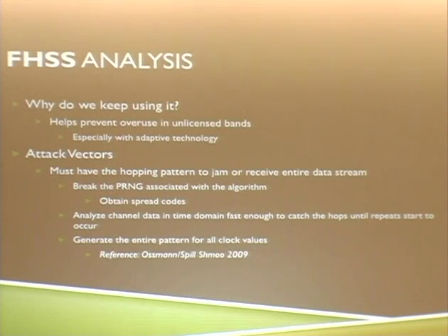So, frequency hopping analysis: why do we keep using it? It's very efficient, and what I mean is it keeps a lot of noise out of the bandwidth, right? There's an overuse problem, or people suggest there are overuse problems, in unlicensed bands, anything from 900 megahertz or any of the ISM bands. It's really good to use frequency hopping in those bands, and it is a good idea, because it keeps things on different carriers and not on the same frequency range as if you were some type of licensed protocol. So in that aspect, it is ideal for efficiency, but not security.